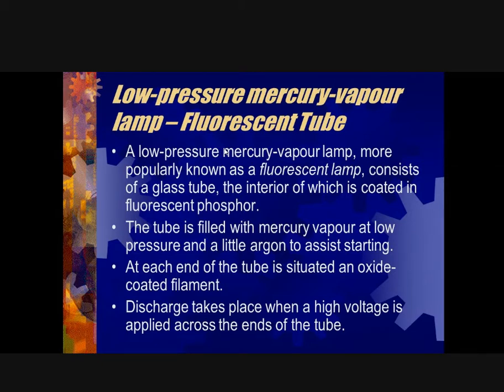So when you are buying a replacement tube for LED, it's always best to take out the tube that is there, look at the T type, whether it's a T8 or whatever number it may be, and try to replace it with the same one. However, if that's not possible, you can always modify the connection to fit the type of LED bulb that you get.